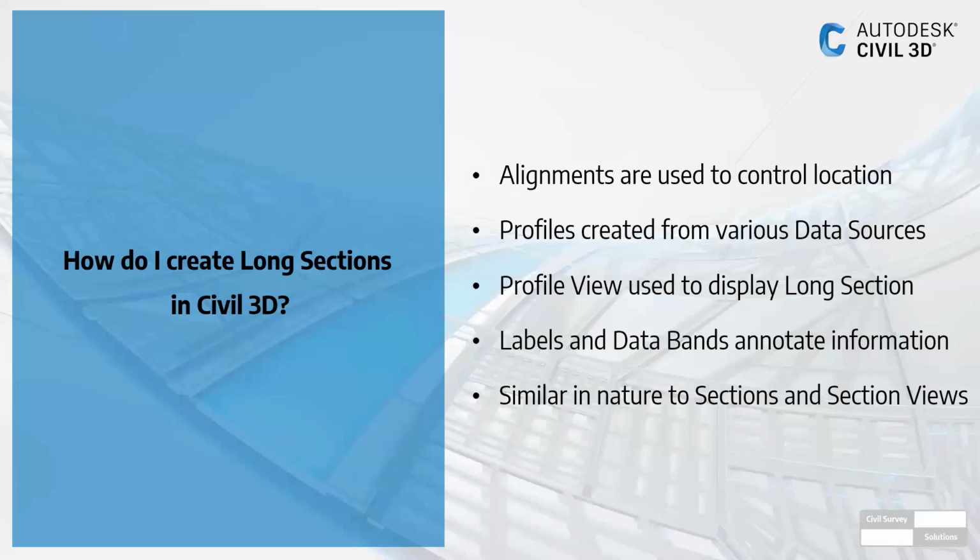Like all Civil 3D objects, labels and data bands are used to display information in various ways. So the label is just normal annotations that you would drop in over the view or over the profile. The data bands are tables of information that you would attach to your profile view. Now, the way these function are very similar, or almost identical in nature to the sections and section views.